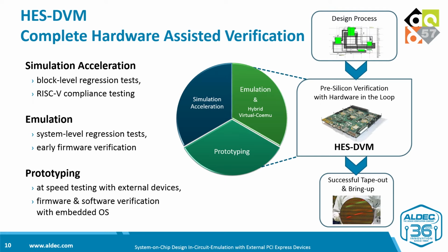At the beginning, when RTL modules are created and simulated, the FPGA board can be connected with the simulator. In this configuration, complex and long simulations can be accelerated for the benefits of hardware design and verification teams. Moving to hybrid co-emulation allows for system-level verification of the entire system on chip. At this stage, the FPGA board can be connected either with the system-level test bench on the host workstation or with the virtual platform or even with external peripherals.